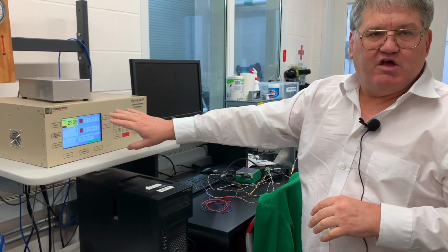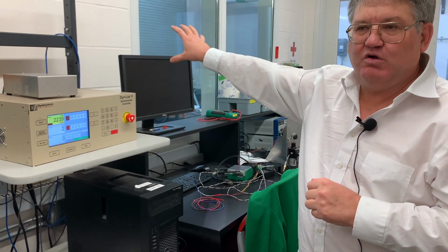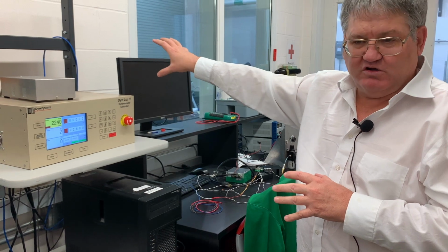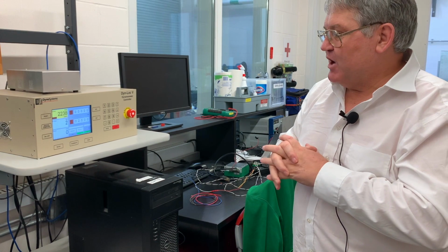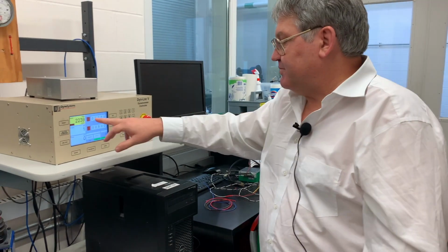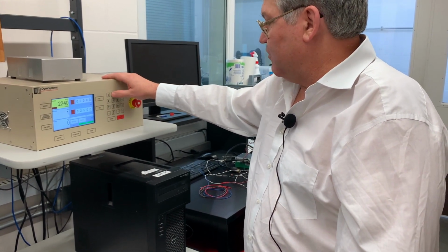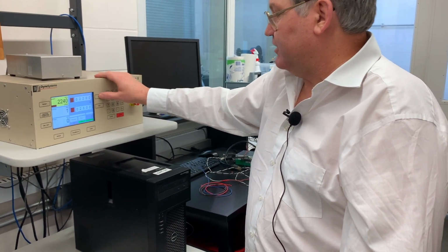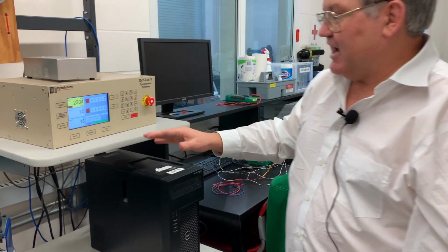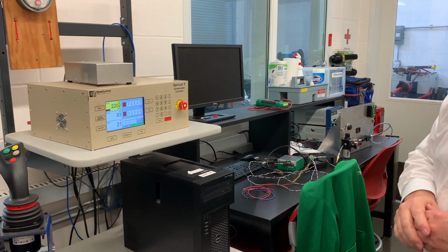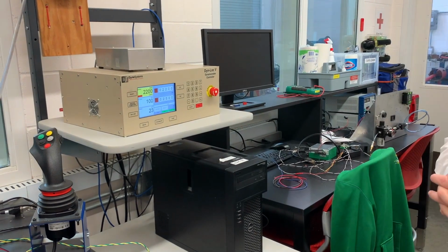So I can set the engine speed I want the engine to run at, and then the controller will control the current going to the coils in the dyno and change the torque for the engine to reach the speed. So I'm just going to set the speed roughly 50 RPM below what it is running right now. So we're going to go to 2200, set the speed, then I engage that speed, and you notice it's increased the load, and the torque has increased to 95 Newton meters, and that is at 2000.